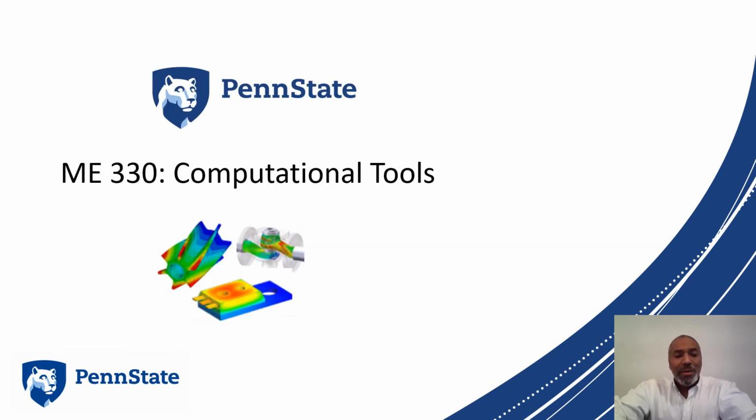All right, so that's all I have on that one. Please, as you go through the application packet, the tutorial for this plate with the hole in the next lecture, take care to think about all the stuff that you're applying. These boundary conditions, we're applying to a linear model, so the material model itself doesn't apply any stress concentrations, but the geometry of the hole does. And as we're creating that geometry, we can calculate what the analytical solution should be, and we want to check out what the simulation does to see how they compare. That's going to be the ultimate goal.